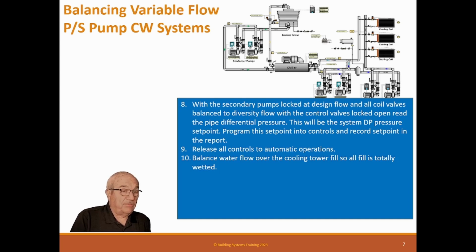So we need to have enough water, and that's why a designer should never have two chillers on one tower where the flow changes. Say you have two chillers that have 200 GPM each of condenser flow, and you have one on and it puts 200 GPM, you turn the other on and it has 400 GPM, that won't work because it'll scale the tower seriously. So we want it wetted entirely. If it's off, it can dry, that's not a problem. But when it splashes, it wet dries 100 times a day, and that's not a good thing. So we don't do that.